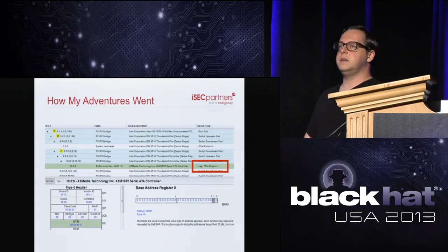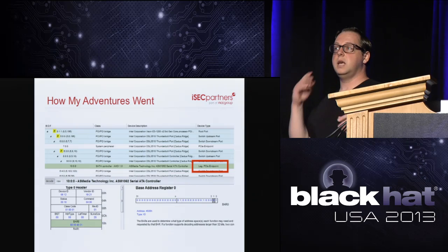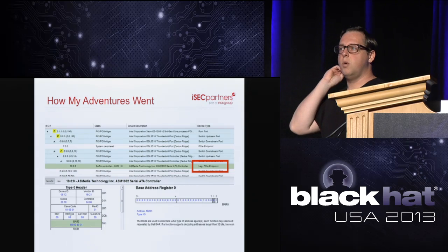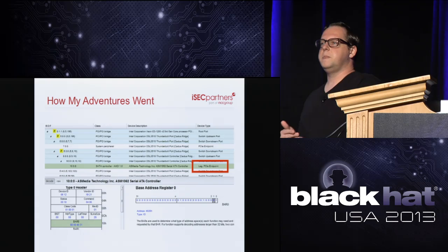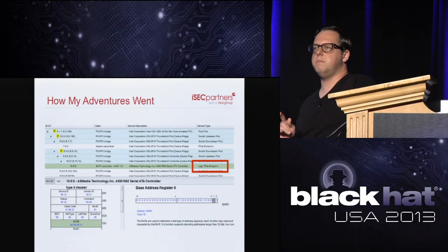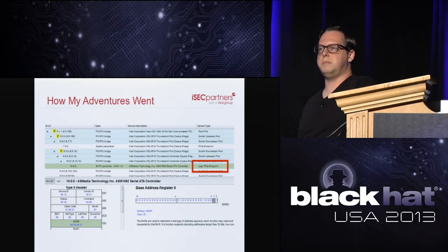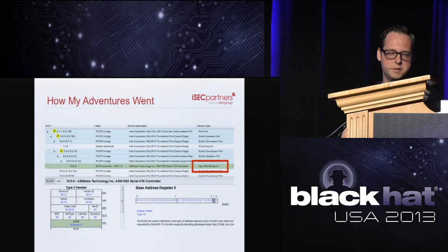And a fun fact, back in the day, your video card would need access to the video memory in the BIOS, so it needed access to that lower level memory. When they moved up to native devices, that wasn't allowed. Legacy devices were allowed to do that, so they made video cards legacy devices. To this day, most video cards on the market still support legacy PCI Express. So in theory, if the programming was done right, we may be able to take snapshots with this hard drive, because we may be able to read the memory space of the video card, because they're a legacy device.